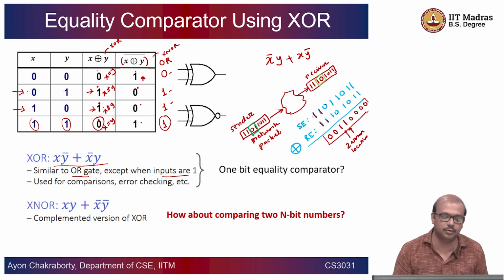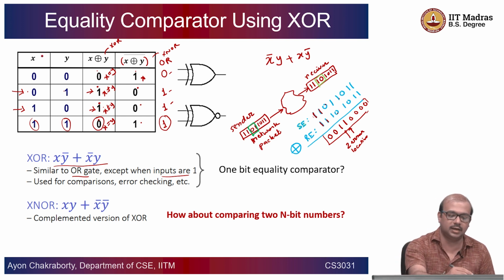because we already have the truth table and we all know how to add binary numbers, just 1 bit binary numbers. You can also interpret this x and y, whenever we get the XOR value, as a sum of x and y. I will tell you how. If you think x and y are two 1 bit numbers.